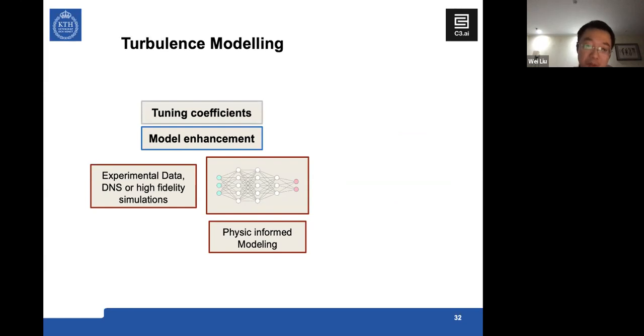So even though improving the turbulence model coefficients is extremely useful, the deep learning algorithm can actually achieve much more when interacting with the turbulence modeling. Research is focusing on new ways of enhancing turbulence models by acting directly on the source of uncertainties, such as the closure modeling and the evident failings of the eddy viscosity hypothesis. An idea is to use a deep learning algorithm to build a representation of turbulence modeling closure terms. So it basically learns the behavior of the turbulence. Therefore, enhancing the model is a more general and advanced, but complex approach.